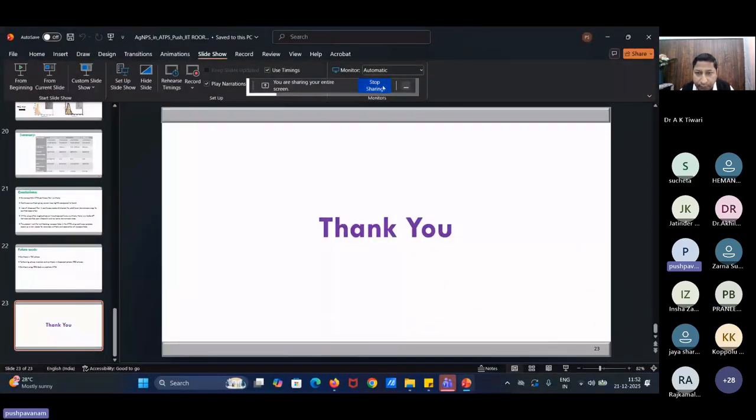Sir, am I audible? Yes. Good morning, sir. I'm Pranil from IIT Guwahati. Firstly, very interesting talk. I have a very small question regarding the capture efficiency between the two phases. What is the typical Marangoni number, or say the Damkohler number? Because if you are considering slugs, and the capture happens at the interface, are Marangoni effects pronounced, or the surface renewal rate, how does that affect the capture efficiency, which matters for scaling up?